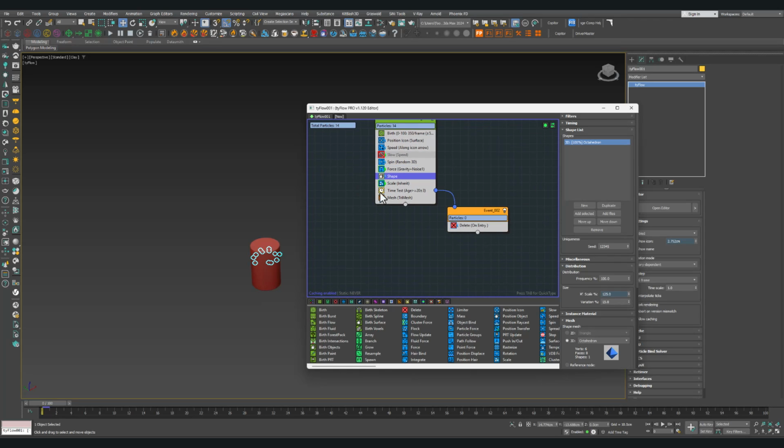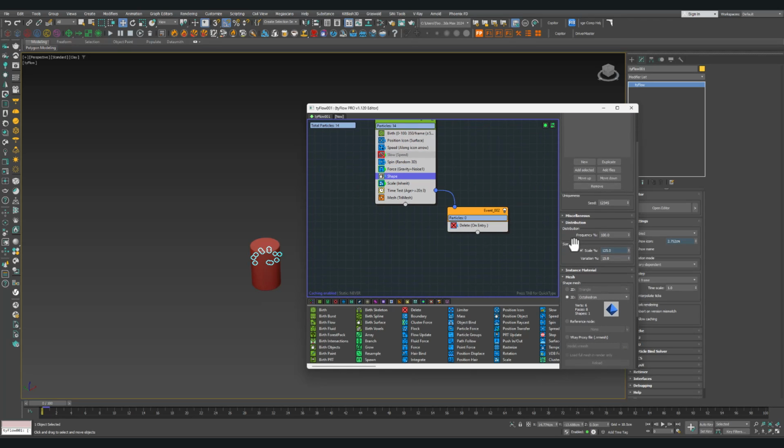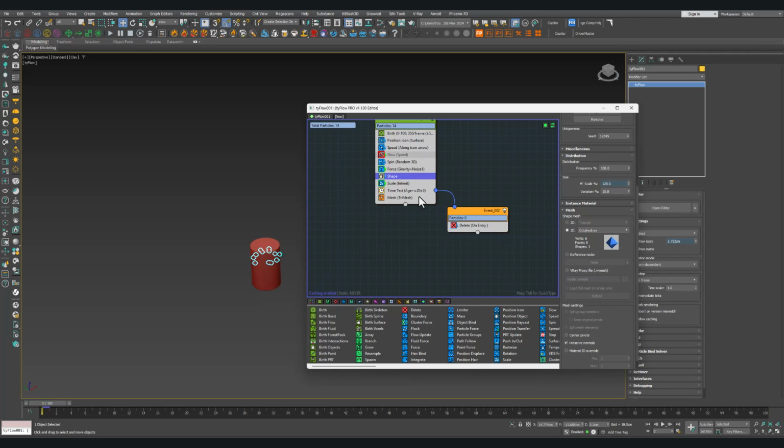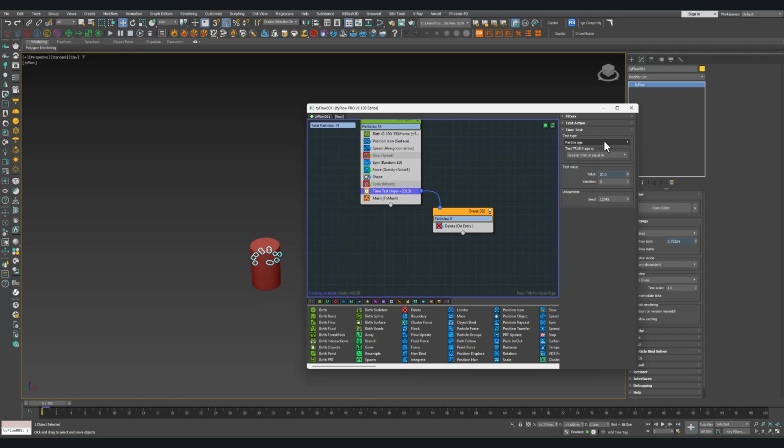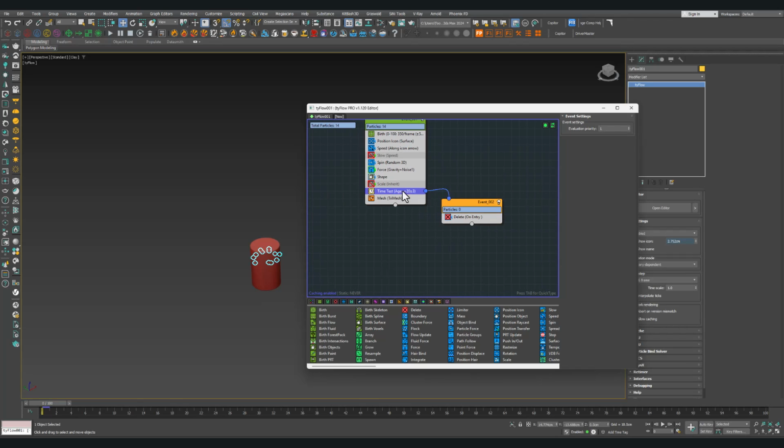Shapes to turn the particle into the shapes. I used a 3D octahedron, and you can use a scale or not. It depends on you, it depends on your desire. And then add a time test, a condition operator, put it to the particle age just like before, and delete the particles. Also, you can use the property test and tell Tyflow that blue.